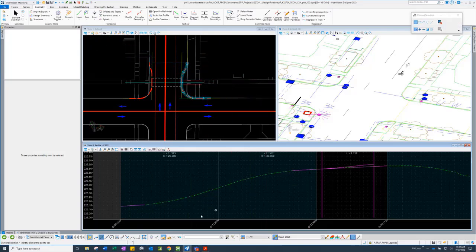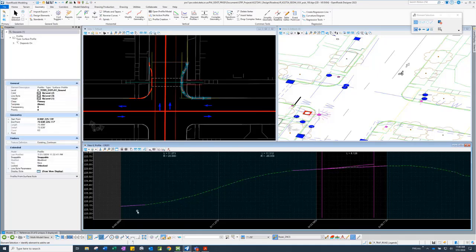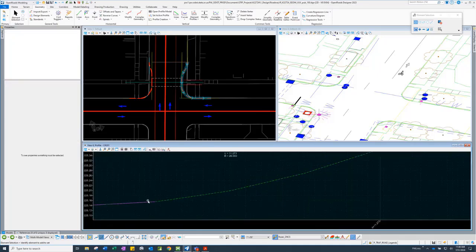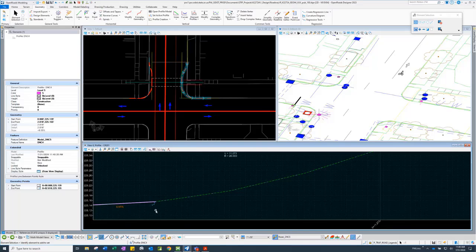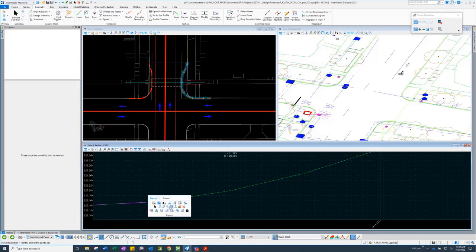Yeah, tangents. Yep. And so you can, from this, there we go. Even though it's snapped there, again, you can trim extend it, but you lose the snap. So instead of doing that, you want to hold the snap, but extend the line to get your PI point, right?